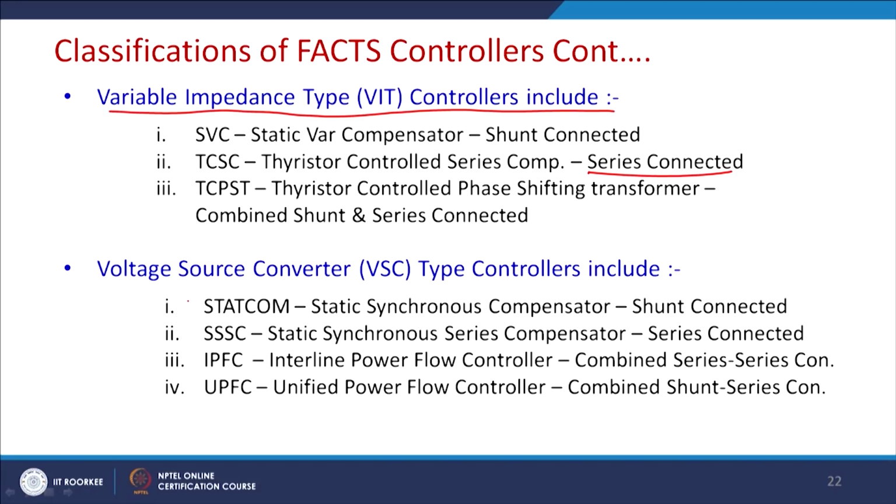are voltage source converter based. These are STATCOM, which is shunt connected, and SSSC, which stands for static synchronous series compensator. Thereafter you have the interline power flow controller, which is a combined series combination, and thereafter you have UPFC, that is unified power flow controller, or UPQC, unified power quality conditioner. For power quality we say power quality conditioner, and for FACTS we say power flow controller.